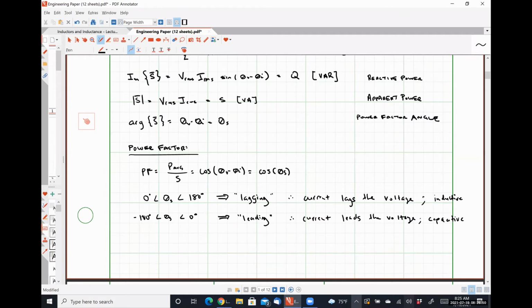So they fine you if your power factor is too low, because they're spending money to generate apparent power, but you aren't paying for it, okay? So they'll fine you for the increased costs in the infrastructure necessary to do that. That cost may come in having to use larger wires to send the increased amount of current. So if you think about the utility distribution company, they're providing a specific voltage to your home, residence, business, whatever you want to call it.